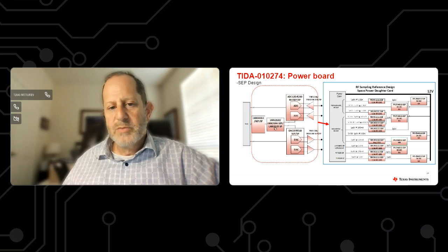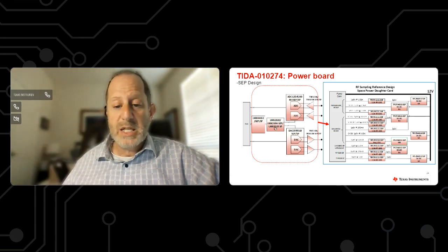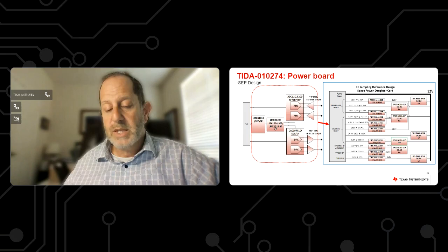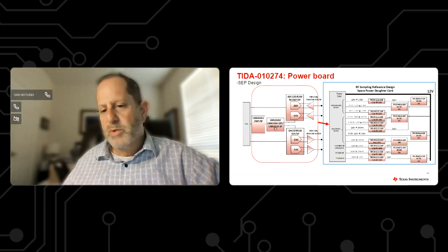So this is one of the advantages of the reference design, is that you can kind of see and get a glance at the way that we've done some of the layout work, keeping LDO outputs separated from switcher outputs and things like that in order to minimize noise and spurs from those solutions.